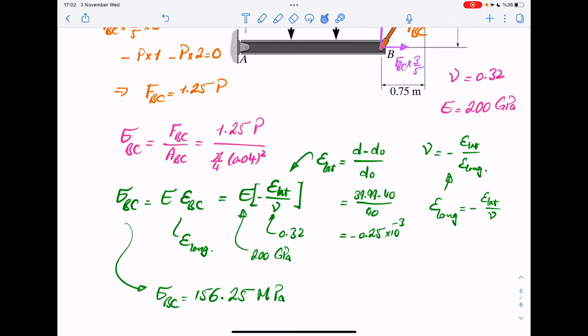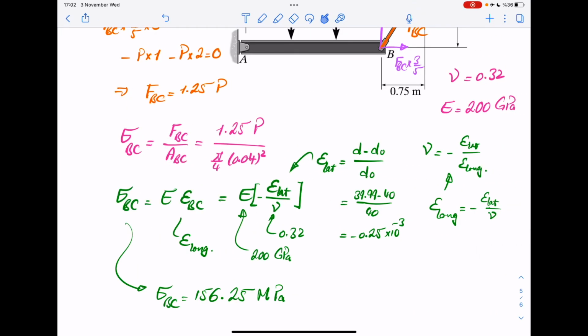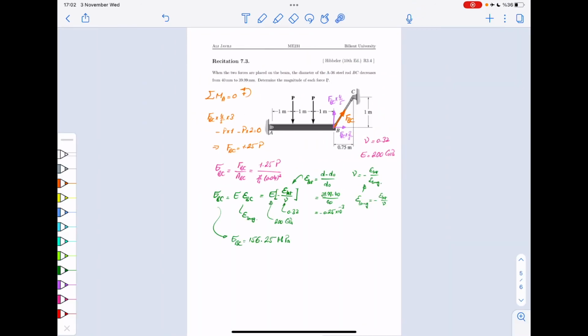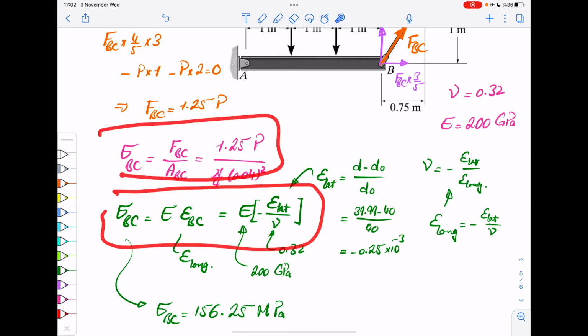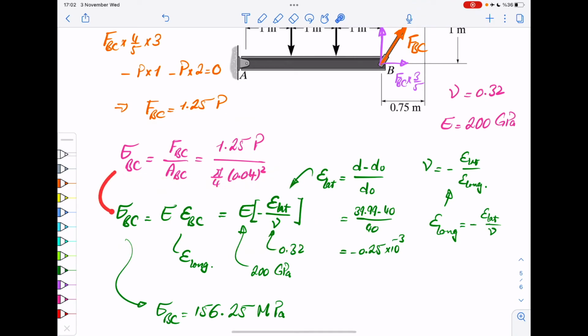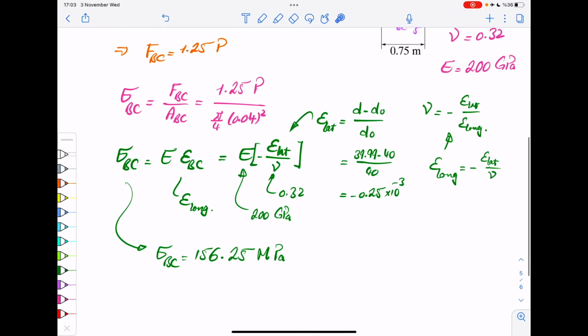This is very interesting, this example. This is your stress-strain relationship. This comes from your equilibrium, okay? They all have stress in them, but stress is now the connection between the two. So what you need to do is simply to set these stresses equal, because it's the same stress, and then you can calculate P, okay? There is only one little step that you should usually check.